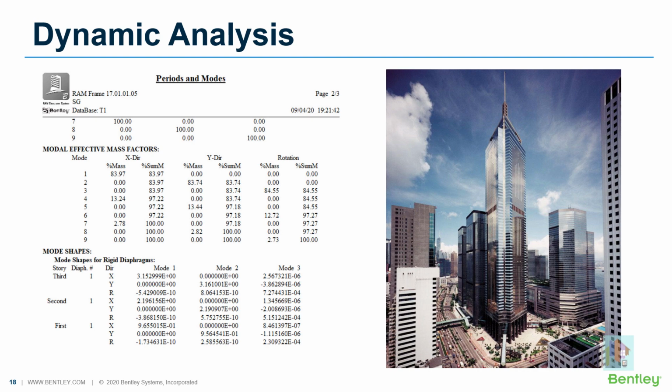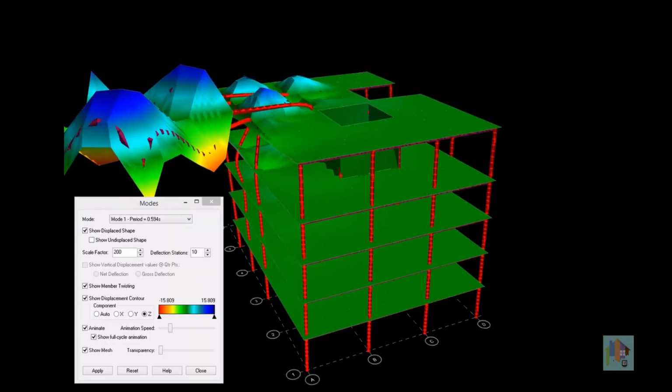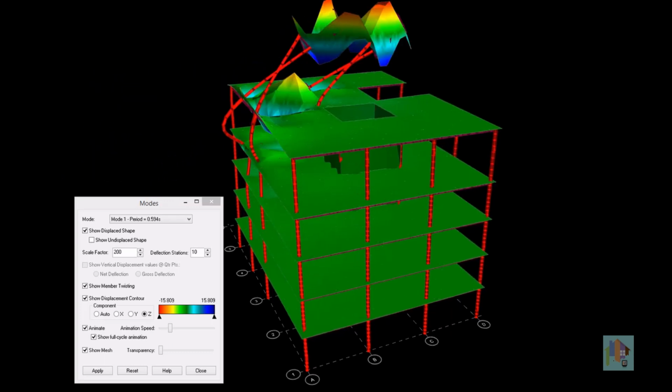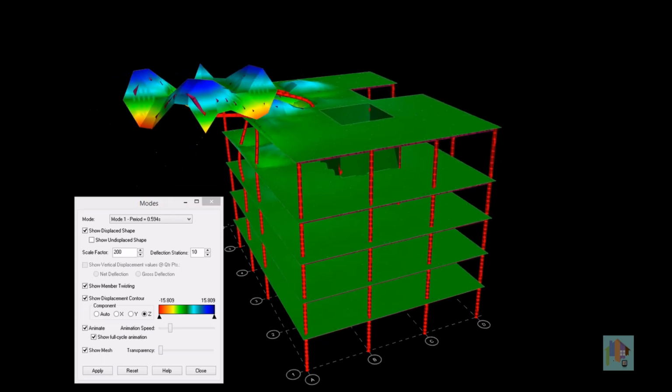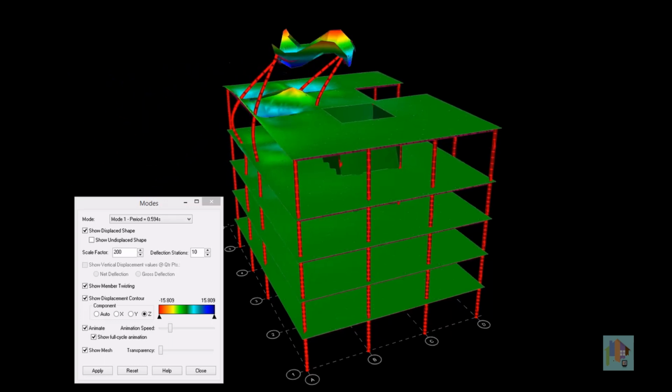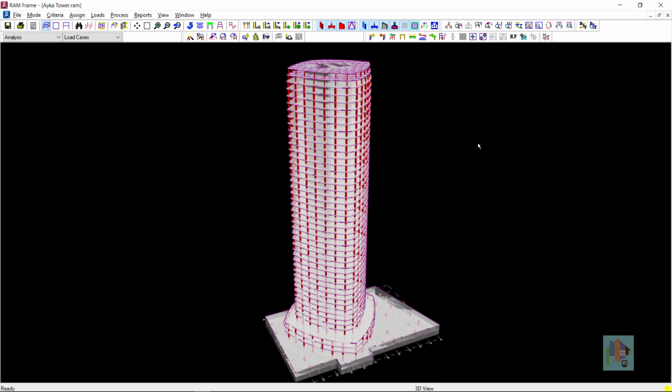Now, if there is any smaller structure present in the tall building, like an antenna or a tower on the roof, that contributes significantly when the structure is oscillated due to earthquake. There might be several hundred local modes for which only these isolated structures participate, and participation of the rest of the structure is insignificant. This eventually increases the number of modes considered. As you can easily understand, these local modes do not contribute anything to the overall mass participation if the main building remains idle. So overall analysis time increases due to consideration of a higher number of modes.